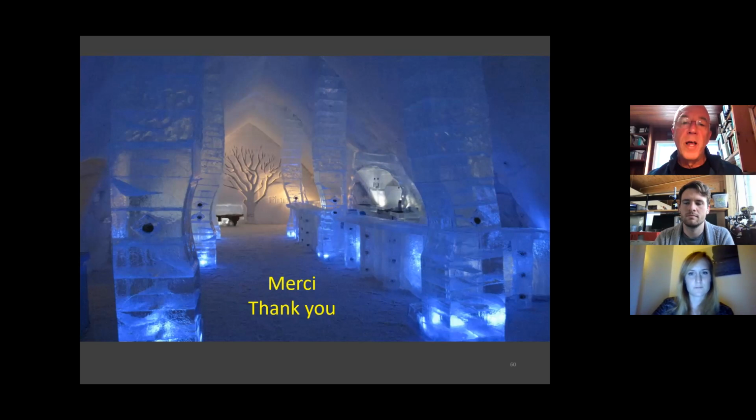The good thing about cellular glass, and there's also an equivalent material like expanded clay, for instance, is that it can be used as a granular material. So you can put that in a layer in the system. And you can even design your system so the granular materials are big enough to generate convection. So that will add some efficiency in the winter using convection. And in the summer, it's going to be a very good insulation layer. So you can have a material that will work both in the winter and in the summer. But there's not yet any experiment using cellular glass or expanded clay in a permafrost environment, to my knowledge.